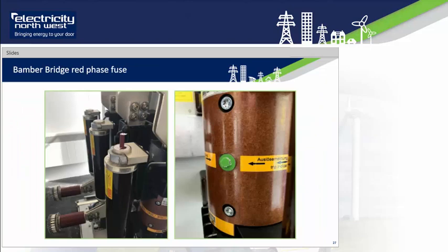Just to give you some visual examples, the photo on the left is the withdrawable carriage of the IS limiter, which shows the three IS fuses and inserts. The IS limiter is a combination of an extremely fast-acting switch, which can conduct a high current but has a low switching capacity, and a fuse which has a high breaking capacity mounted in parallel. In order to achieve the desired short opening time, a small explosive charge is used in a stored energy mechanism to interrupt the switch, which is shown on the right picture where the green dot shows a trip indicator.